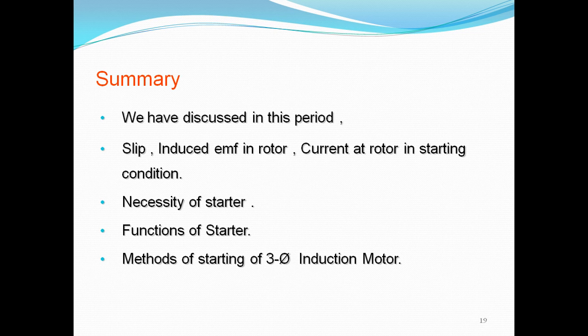There will be some interlocking to ensure proper sequential operation of the switch and starter. So this method not only limits the starting current but also increases the starting torque. Why? Because the torque is directly proportional to and depends on the resistance.